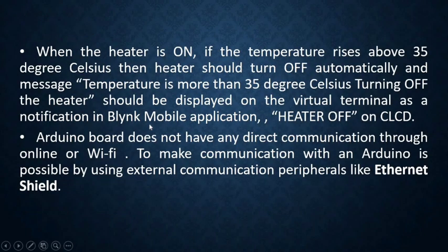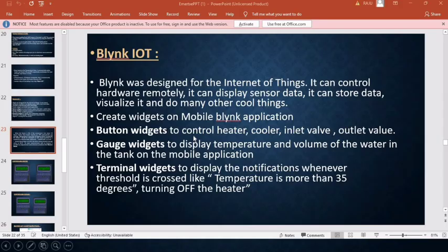When the heater is on, if the temperature rises above 35 degrees Celsius, then the heater should turn off automatically and the message will display as temperature is more than 35 degrees Celsius, turning off the heater. It is displayed on the virtual terminal as a notification in the Blynk mobile application. Heater off on CLCD. Here, the Arduino board does not have any direct communication through online or Wi-Fi. To make communication with an Arduino possible, we use external communication peripherals like an Ethernet shield.